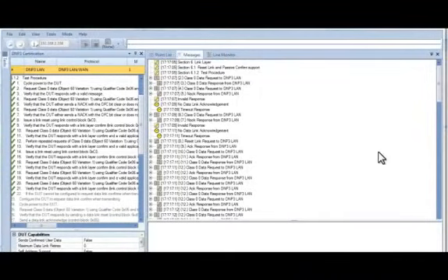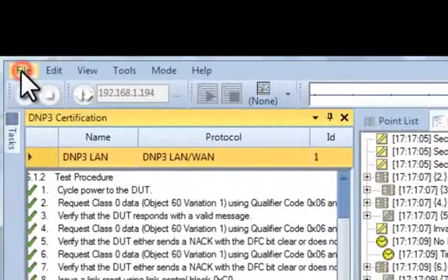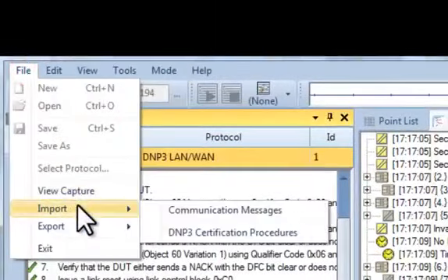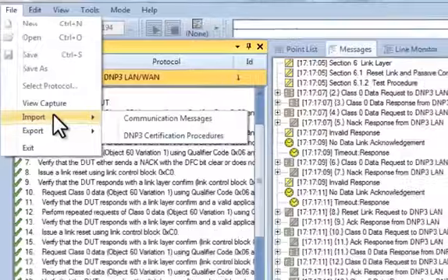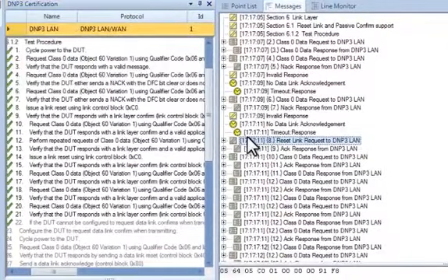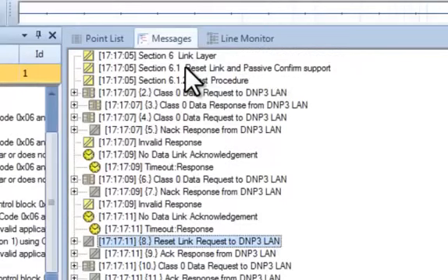Test results can also be viewed in the ASE2000. The screen shown is as it was right after the test ended. This layout can be restored by importing the MSGX and test result XML files we previously exported. Notice that the messages view contains test section numbers showing where each test started, and individual steps are contained in braces.